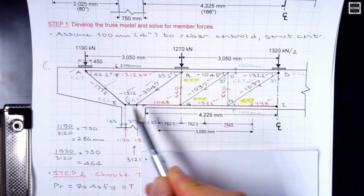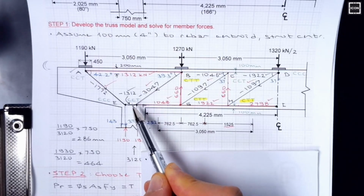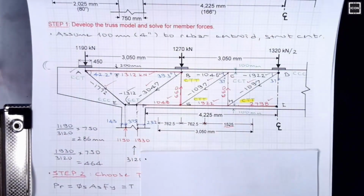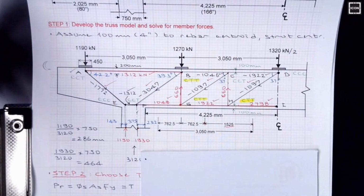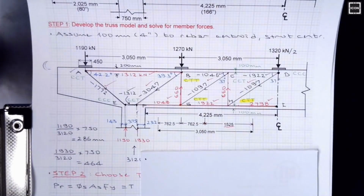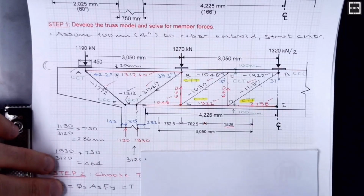My third reason is the ease of checking the nodal zones, because if you only have one node, it's going to be really troublesome to do the checks. You want to isolate the forces as much as possible. That will really expedite your check. So because of those three reasons, whatever example you look at, whatever procedures you follow, you will see those multiple node situations. And the trend is like this. You might see some older models maybe not really doing this separation, but the newer models, definitely we would like to separate the nodes.